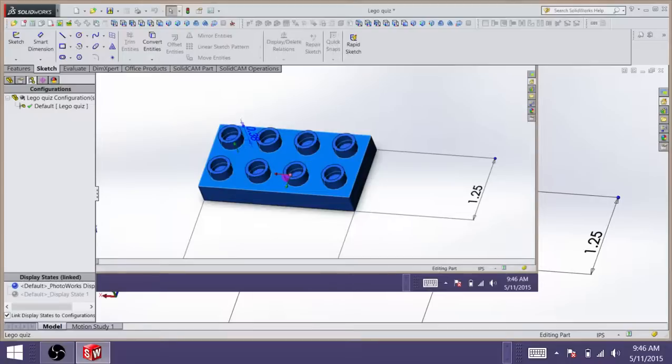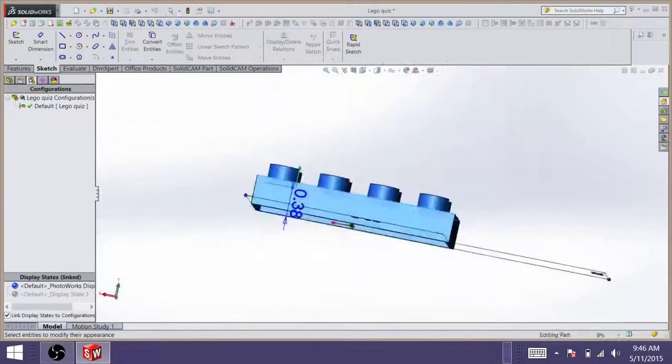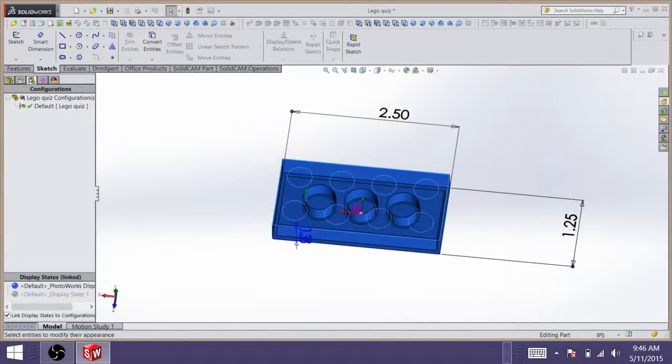You've got the configurations. In SolidWorks, you can make multiple configurations. Let's say you had your part and you wanted to really quickly toggle between views: I want to look at this part of the part, like the bottom, zoomed in this way, with this color, with hidden lines shown, but then really quickly toggle to another view. You could make multiple configurations.